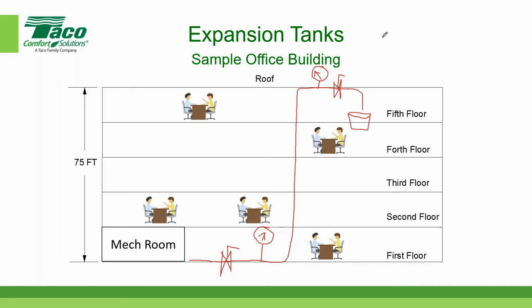Well, that's true. At the bottom, if I just fill the piping system with water and I don't turn anything on, I don't have anything expanding, I'm just measuring the pressure, I'd read approximately 32.5 at the bottom, and somebody had the correct answer, that would have 0 at the top. We don't want 0 at the top. We want something greater than 0. I'm just going to put 0 PSIG at the top here. We want something greater than that.